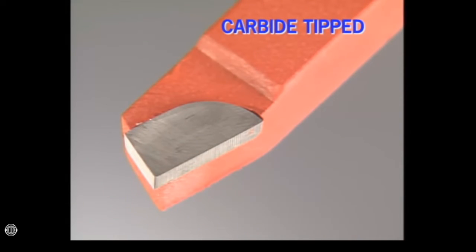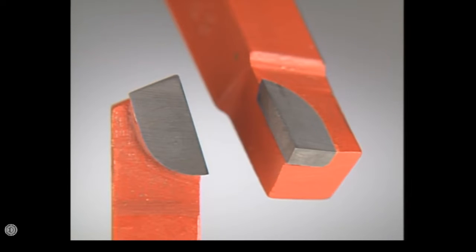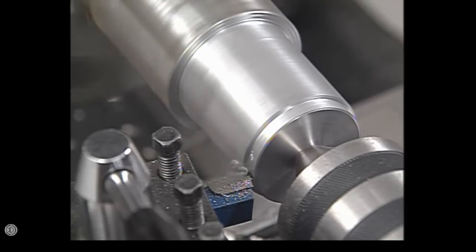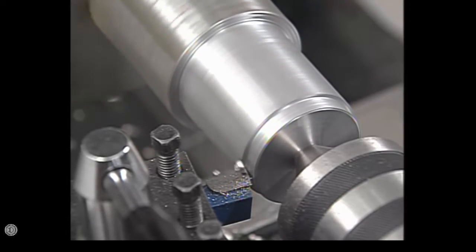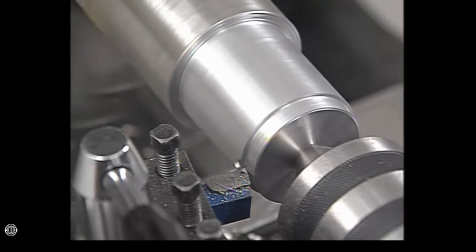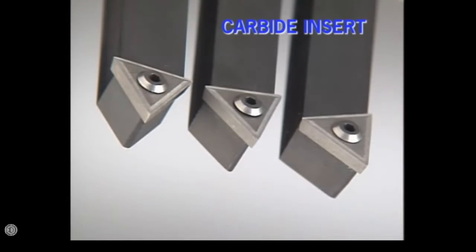The cutting edge of a carbide tip tool is brazed to the end of a steel shank. The shape of the cutting edge, its profile, and cutting angles are manufactured into the tool. A little cleanup on a green wheel, a silicon carbide grinding wheel, and the tool is ready to go. Cemented carbide will handle much more heat than high-speed steel, so carbide tools are able to cut tougher metals and cut at higher speeds. Cemented carbide is also used to make small inserts that are clamped to a tool shank.